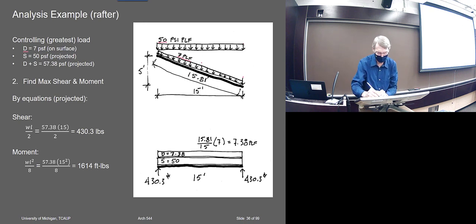I've got a load coming in like this, and I'm trying to span it like this. I'd have to find the component of the load that was actually causing the bending, right? Because in reality, with the load coming in like this, some of it is going into compression. This would be the reality of any slope rafter. Some of it goes into compression, and some of it, the normal component, is causing flexure, only the normal component.